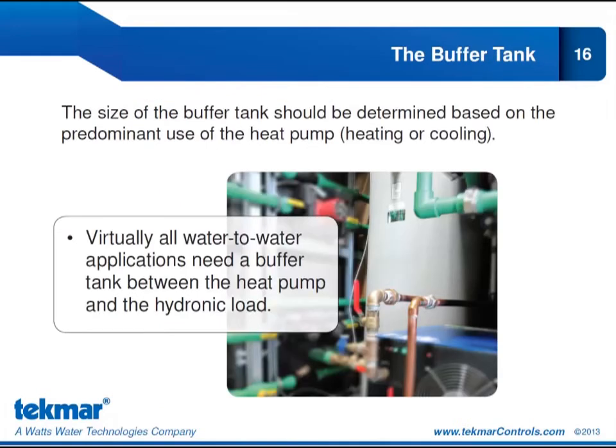Now, the size of the buffer tank should be determined based on the predominant use of the heat pump. So is the heat pump going to be in heating or cooling mode for most of the year? For us in Canada, it's definitely predominantly used for heating. Same with the northern United States. But if you're in the southern United States, you're probably using that heat pump for cooling most of the time. So your buffer tank would be sized for your cooling load in that case.